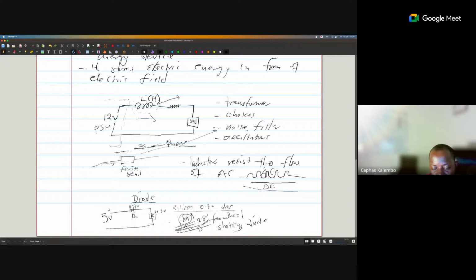The idea is that when it comes to a stop, if you're driving this with maybe 12 volts or 9 volts, you'll probably have maybe 2.8 or 2 volts in residue. Now you have to collect that and dissipate it, because if you leave it in the circuit, it will start overheating. So you need those diodes to be able to do that. That's one way you can use diodes.